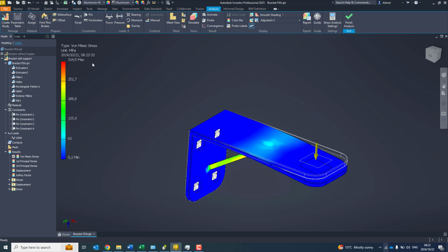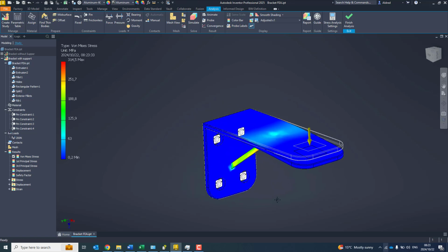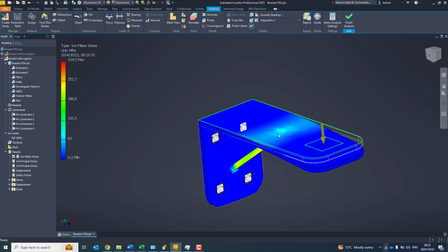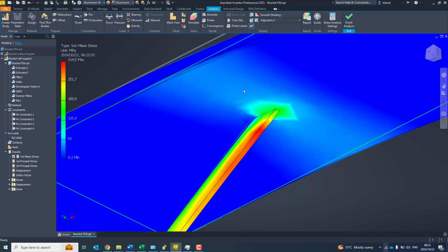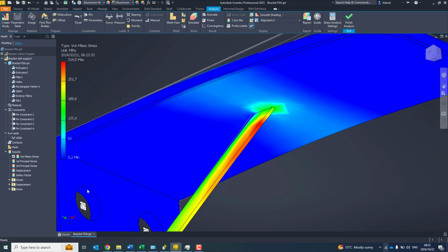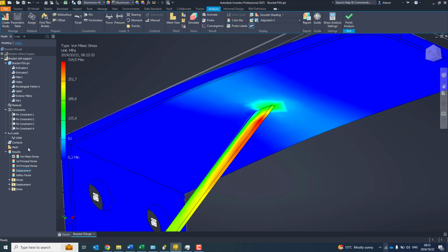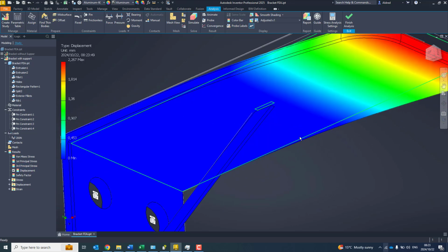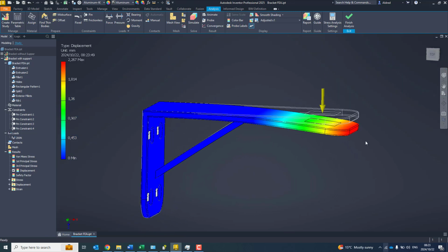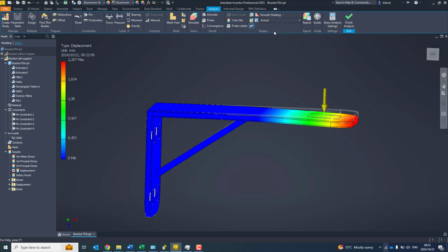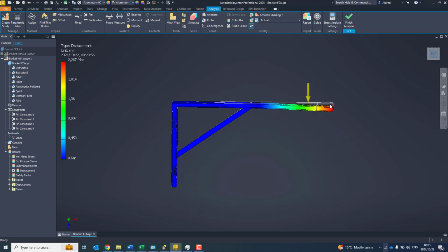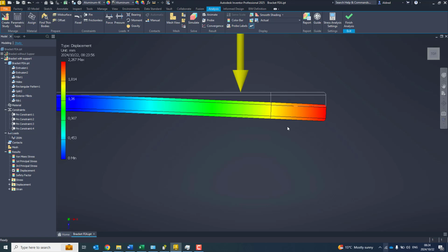And there we go. So it's gone down from, I think, 380 or 370 down to 314, but the stress has now also moved from where the holes were to where the support is. If I go to my displacement, it's 2.2 mils. So it's come down very drastically over there. Let's go to actual. You'll see the actual now is less than that.